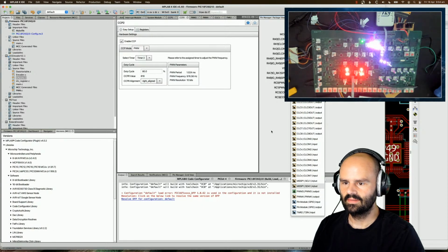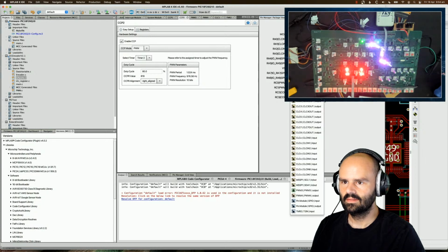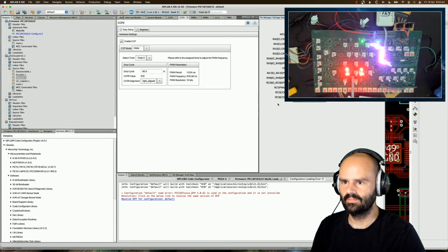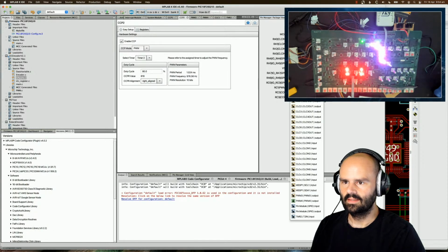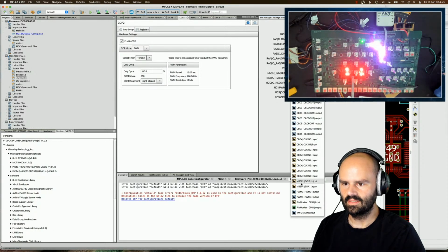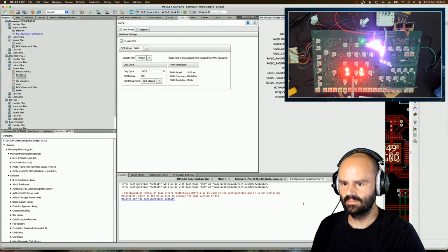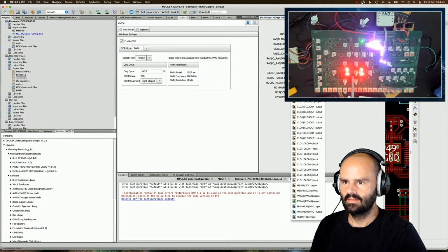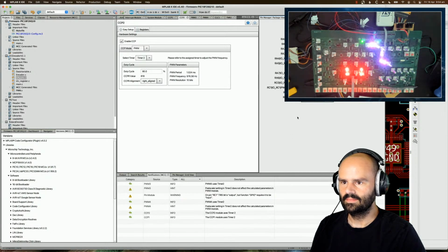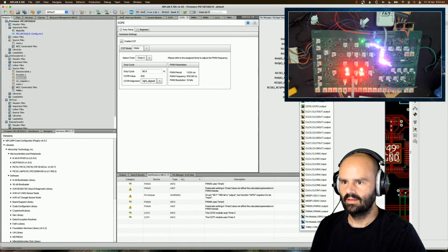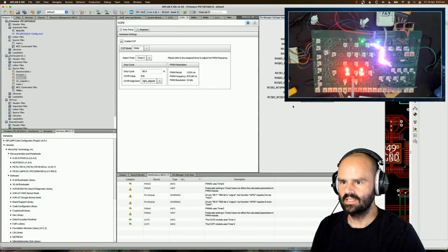How do I clear the pin? Can I not do that? Alright, well, we'll just set this as GPIO output. Actually, to be totally safe, I'm going to set this as a GPIO input. And input. And I'm only going to set up one of these LEDs as CCP1.